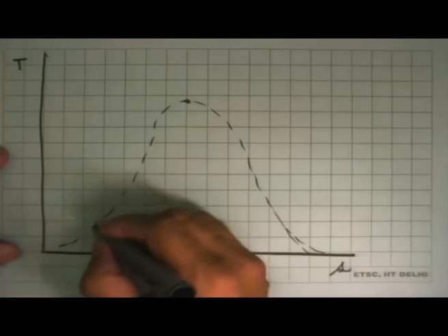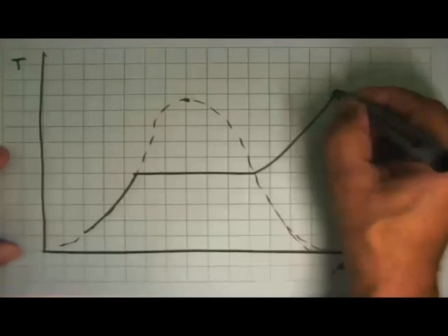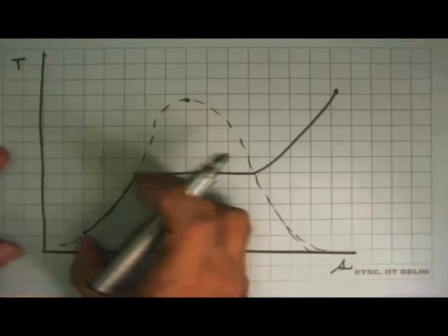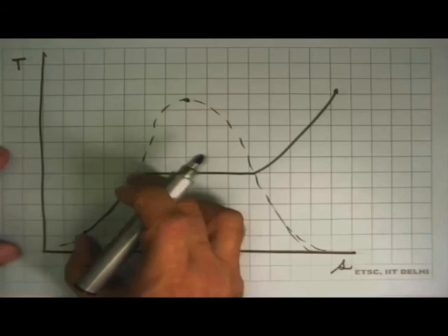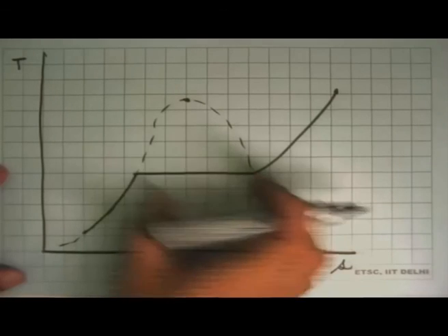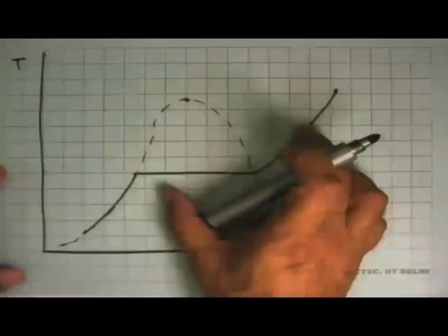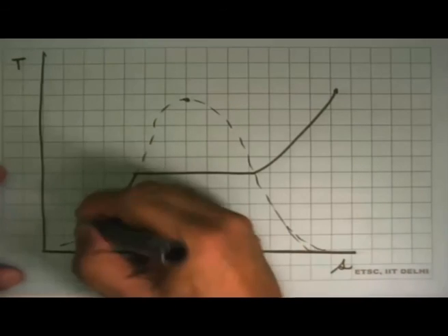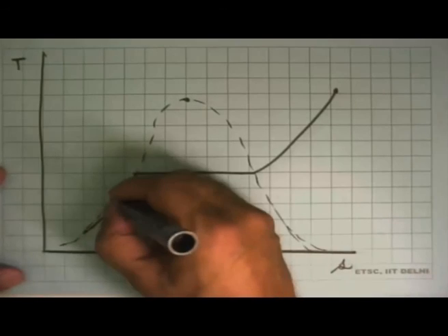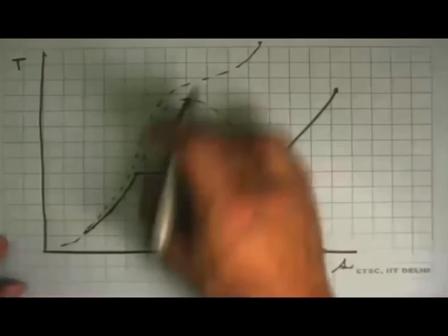If we design something to generate superheated steam, we have to design something that will heat the liquid part. Then we design something that will do the evaporation, where there is a big phase change taking place. Phase change means a big volume change. And then the superheating part. So the design of the boiler becomes a 3-part design. But if you have a supercritical boiler, this will go off like that. Which means I don't need to design 3 different things, only one thing.